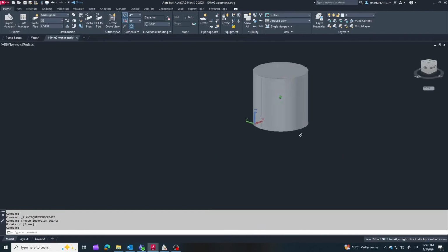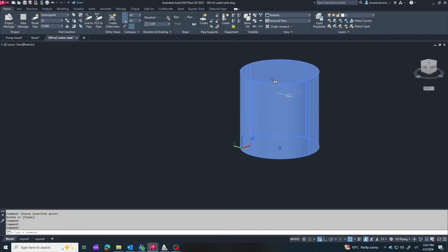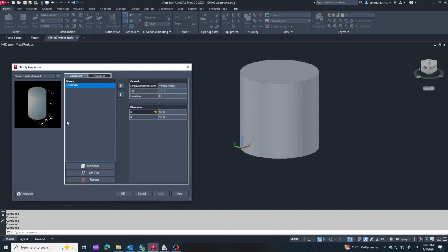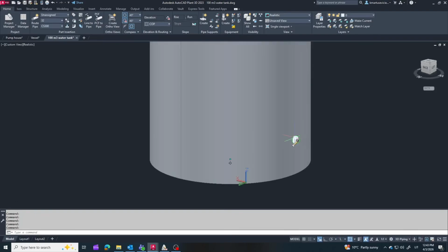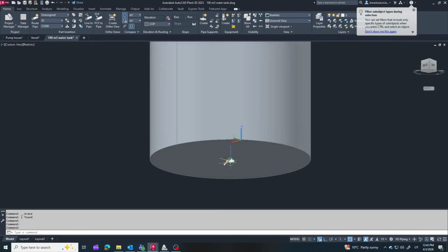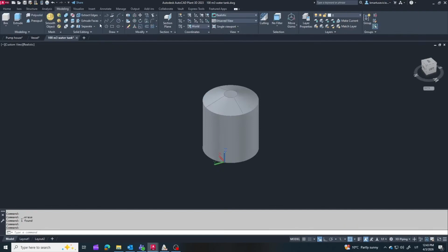With a 5 by 5 meter tank, we get roughly 98 cubic meters of volume. Now let's adjust the conical roof. When we deal with larger tank volumes, the proportions become very important. If the tank is too tall and narrow, we increase hydraulic losses, for example during filling or emptying, and we may also need stronger walls due to higher liquid column pressure.